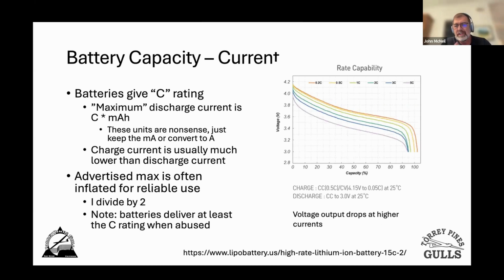Here is a typical unspecified cell at different currents. That was the question, right? What happens is the voltage drops. And other stuff happens we're going to talk about when we get to internal resistance. But basically the shape of the curve is the same. Mostly you can see at the left edge, it's a little different. And at the right edge, things cut off fast. The cliff gets sooner with higher currents. So higher currents are lower.